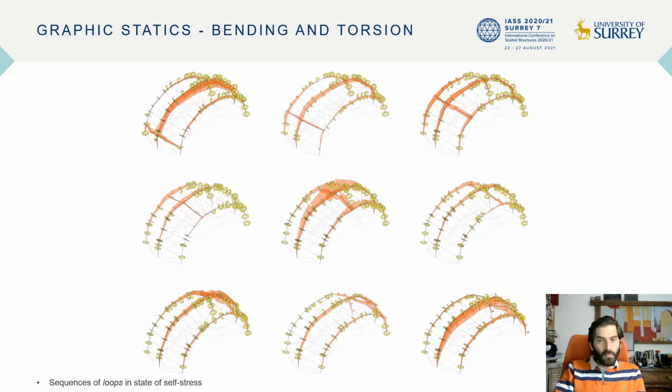Since torsion maximizes shear stresses, material properties provide a maximum allowable shear stress parallel to the grain value for the check. Interestingly, the calculated shear stress approaches the material limit, a fact that highlights the overall delicacy due to the small cross-section and also the significance of having the ability to examine torsion effortlessly with the graphical method.